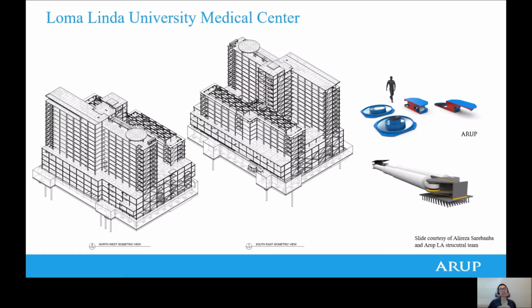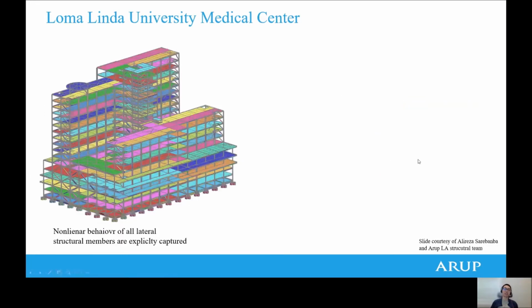In order to demonstrate the seismic performance, as well as do the detailed check of component behavior against acceptance criteria, LS-DYNA nonlinear response history analysis was extensively used in this project. The 3D LS-DYNA model has been established, and all main lateral frames are modeled nonlinearly.